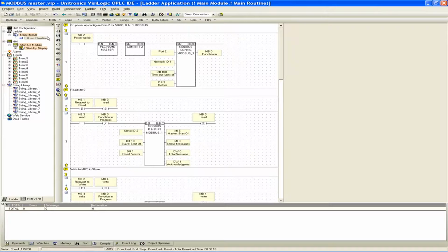which is really all that you need as a condition for any of your configuration parameters that you set up, whether it's the PLC name or, if you're doing Ethernet, any of the TCP/IP card settings or Modbus settings or any sort of protocol that we talk. Any of those conditions just need to be a one-time power-up scan. So I have in my net 1 the PLC name.